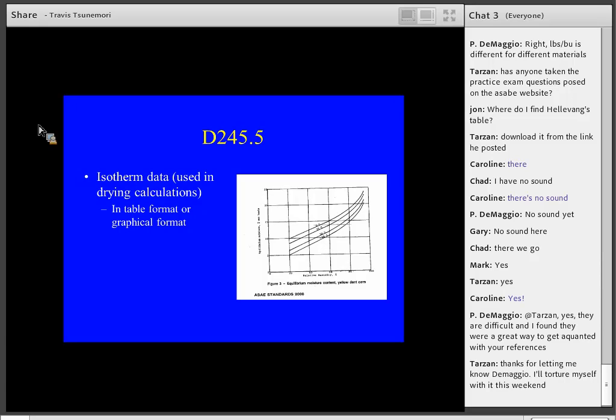have taken several days to allow, at that known relative humidity, at that known temperature, for this material to slowly get to its known equilibrium moisture content when it doesn't change anymore. And they plot these and you can see that for a given humidity, typically things will be wetter. For a lower humidity, things tend to be drier. Makes sense. Interesting, as the temperature goes up, the equilibrium moisture content tends to be lower.